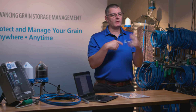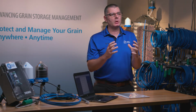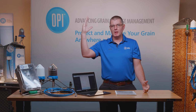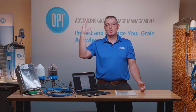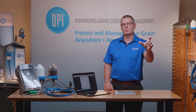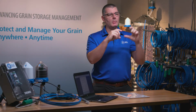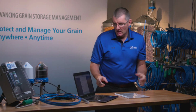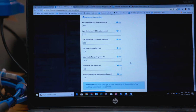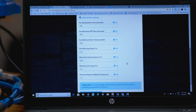There's fan warming once the fan spools up. It heats the air through friction, it creates additional pressure. So the temperature of the air at the plenum is actually different than the ambient conditions or temperatures outside the bin. So we want to measure there because that is the actual temperature of the air being measured. Ambient temperature plus the fan warming gets our actual temperature. So in this particular case, it's set at 300 seconds, so 5 minutes it takes for that to equalize and come up with an actual measurement once the fan warming is calculated.